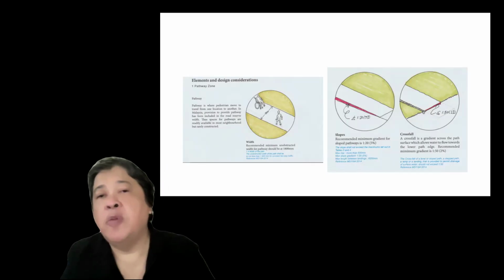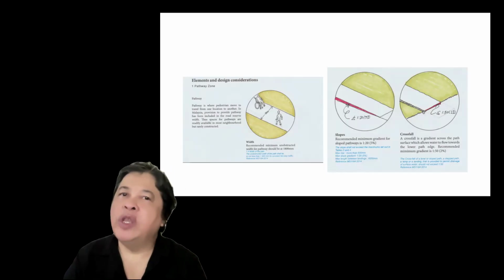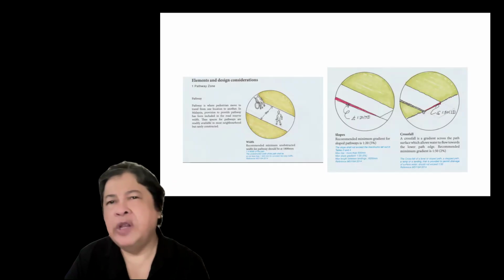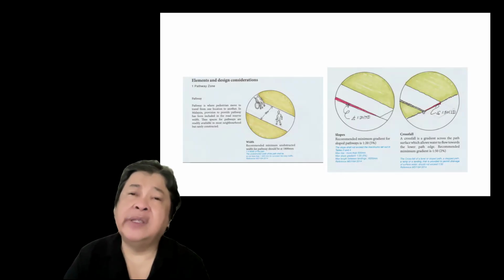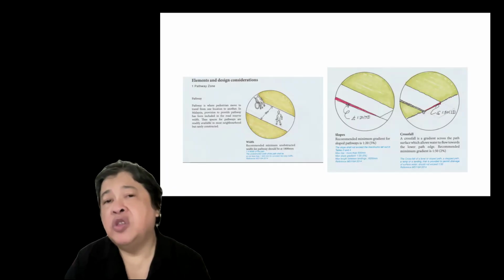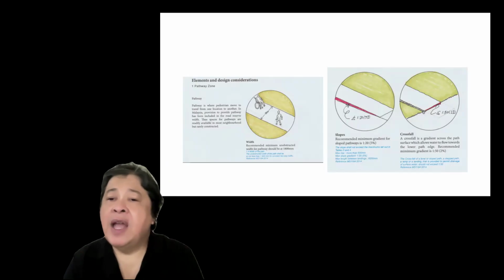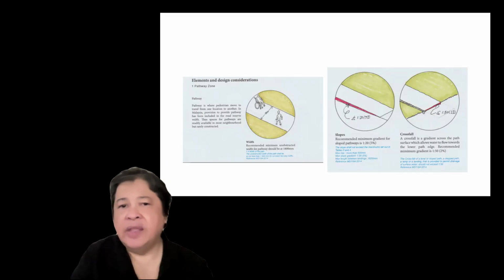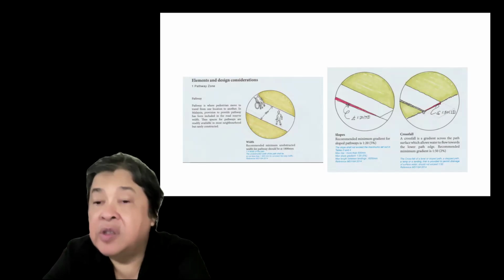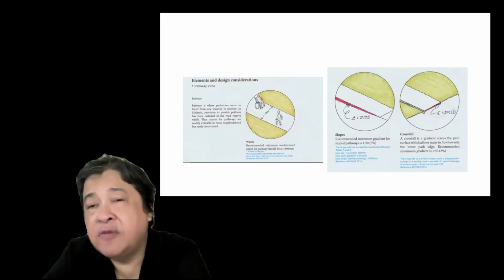As you know, when it's sloping down in the external environment, the best would be a 1:20 gradient. 1:12 is now superseded by 1:14, but it's solely for inside of buildings. So outside of buildings we need 1:20, which is much easier to negotiate. And the camber going against the slope would be 1:50, because it is also important that we get the right sort of crossfall gradient.